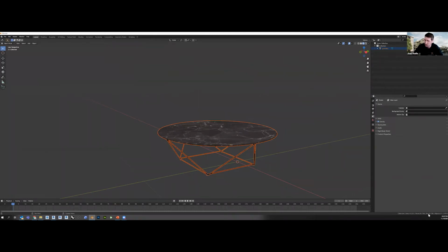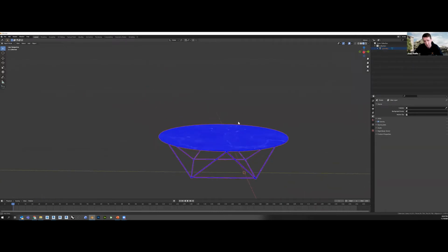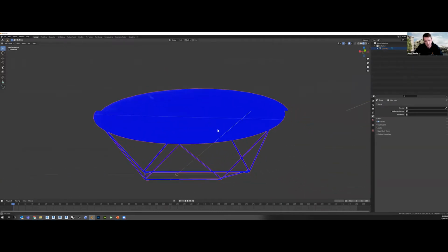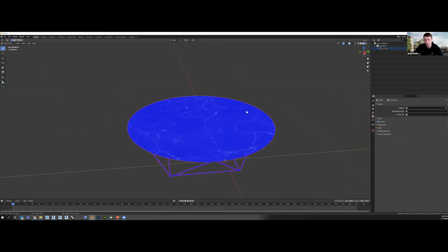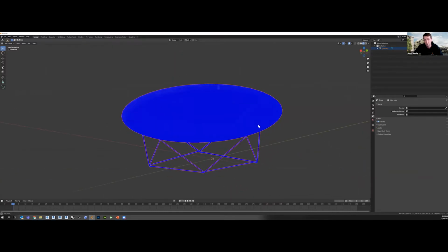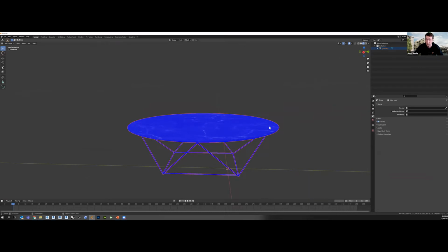Again, we'll talk about this in a second, but this is where you can see how many triangles this model has. And also, if I go up here to my viewport overlay, I'm going to hit this face orientation. If I see any red on any one of these faces here, I'm going to have to go fix that. Again, in the next example we'll look at, we'll see an error in there, but this is just for display inside of Enscape.